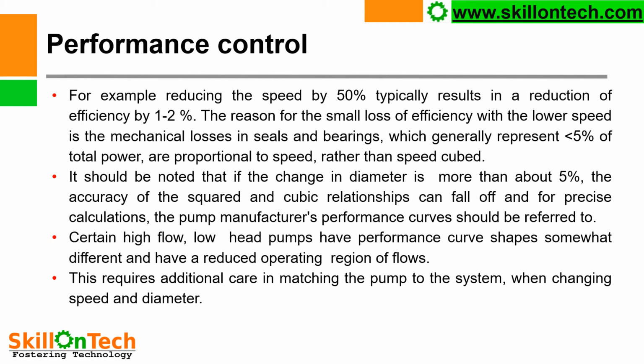It should be noted that if the change in diameter is more than about 5%, the accuracy of the squared and cubic relationship can fall off, and for precise calculations, the pump manufacturer's performance curve should be referred to. Certain high flow, low head pumps have performance curve shape somewhat different and have a reduced operating region of flow. This requires additional care in matching the pump to the system when changing speed and diameter.